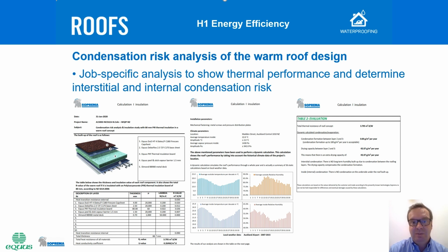In our own thermal analysis, we will take the roof concept that you have designed or specified and look at each individual layer and its R value. This will give us the total R value of the roof concept.